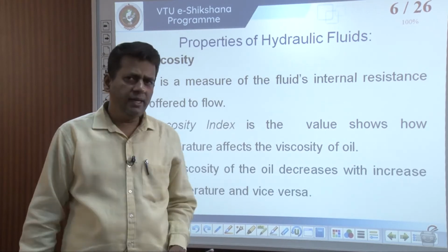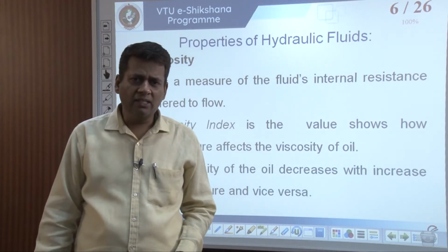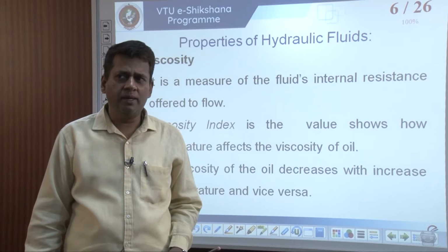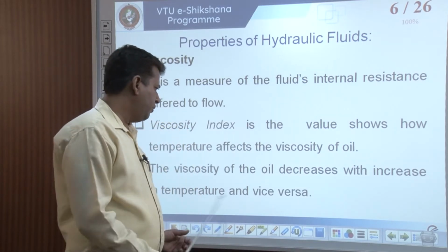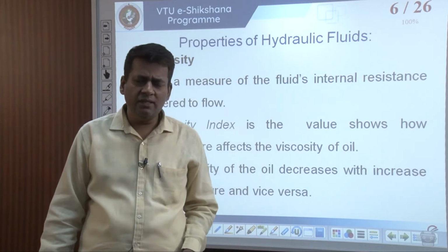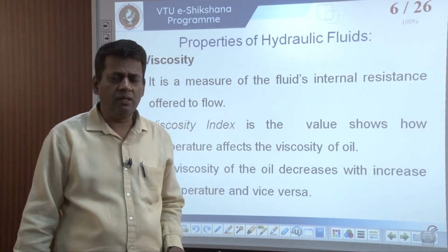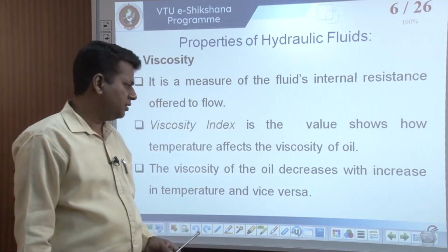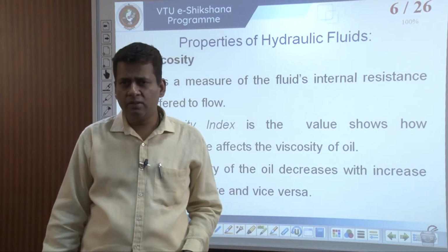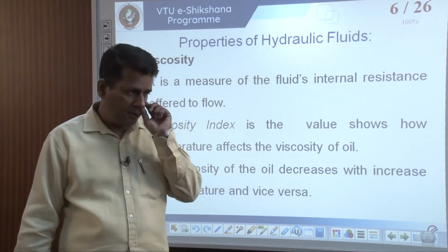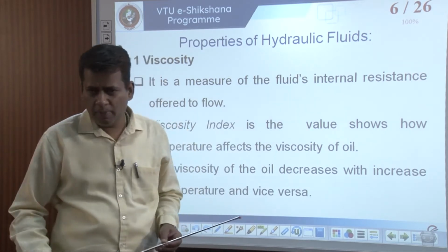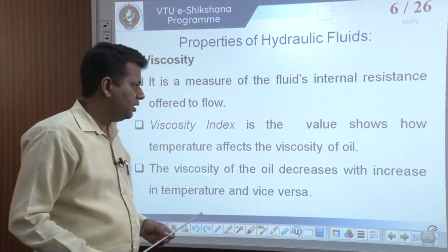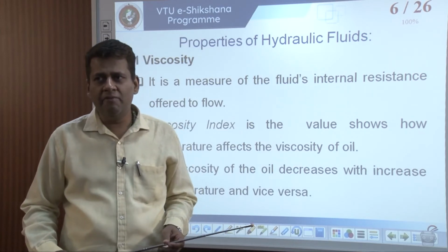The viscosity index should be flat as far as possible within the acceptable temperature range. We know that the viscosity of the oil decreases with the increase in temperature. So, we need to arrest this phenomenon, we need to prolong this decrement as far as possible. That is called the viscosity index and its effect.